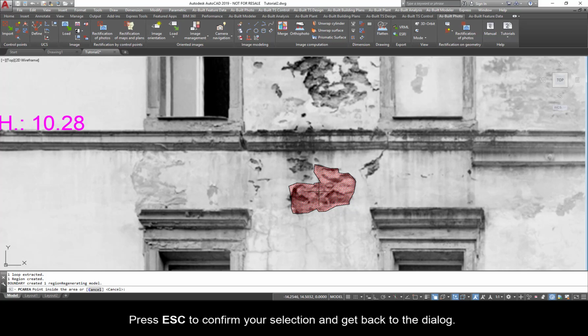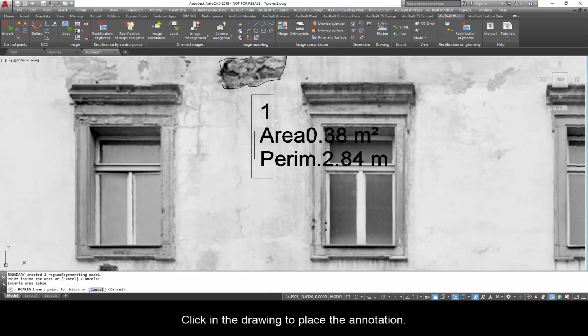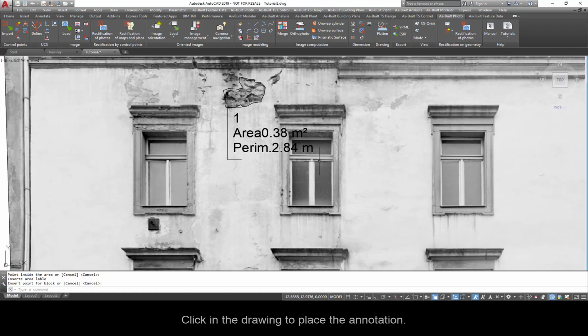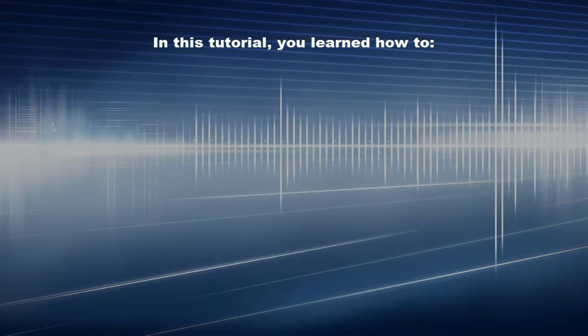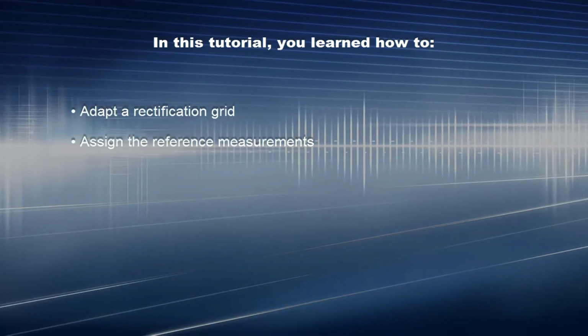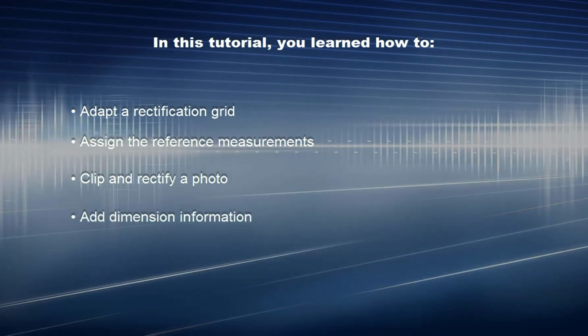Press Escape to confirm your selection and get back to the dialog. Check the Keep Boundary option. Enter annotation text and click OK. Click in the drawing to place the annotation. In this tutorial, you learned how to adapt a rectification grid, assign the reference measurements, clip and rectify a photo, and add dimension information.